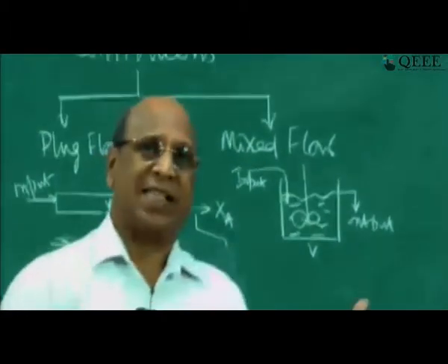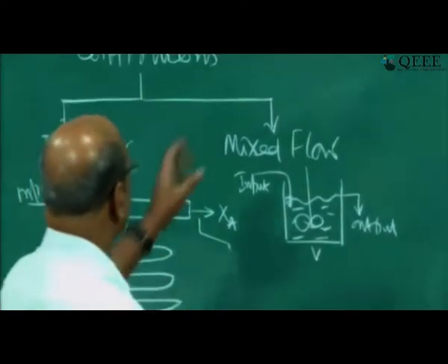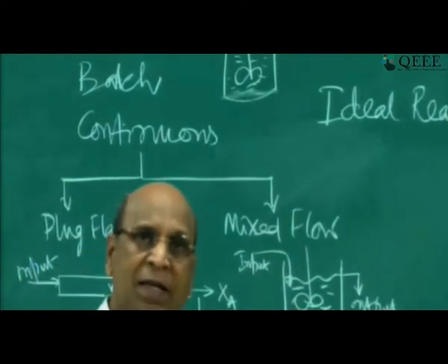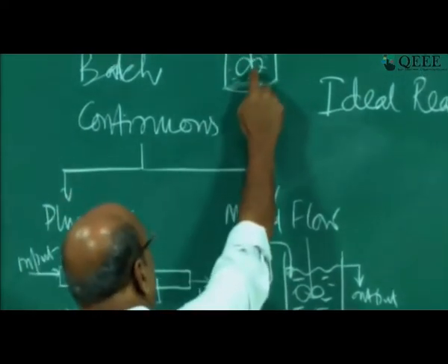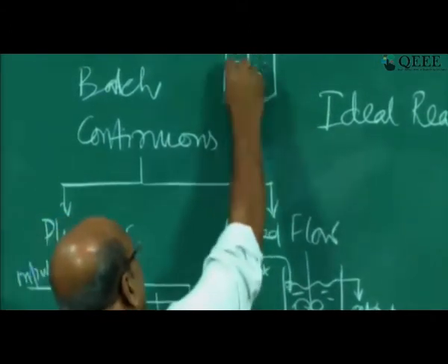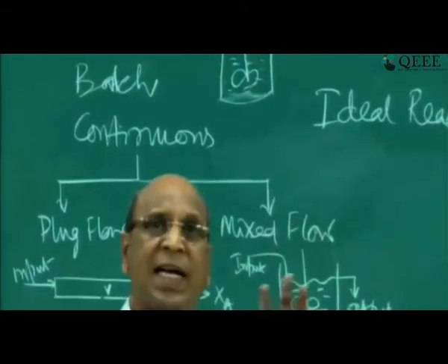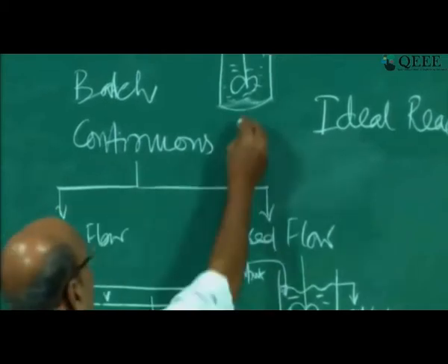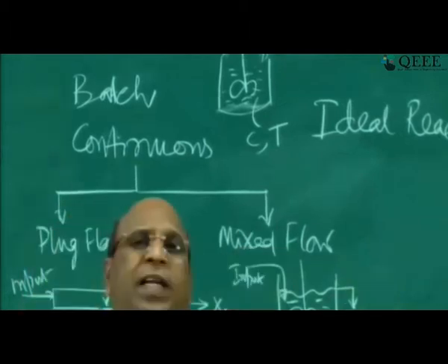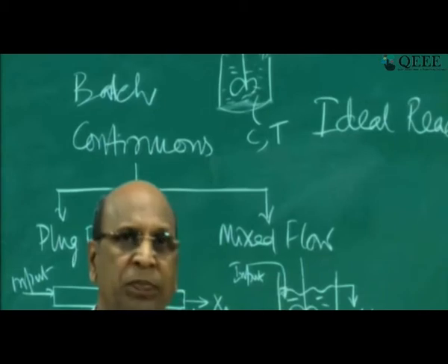So why this ideality? What is this ideality? For example, if you take a batch reactor, the ideal batch reactor will be a tank with a stirrer, and the stirrer is so efficient that when you are stirring inside this reactor, anywhere inside that reactor, the concentration and temperature are exactly uniform throughout the reactor.